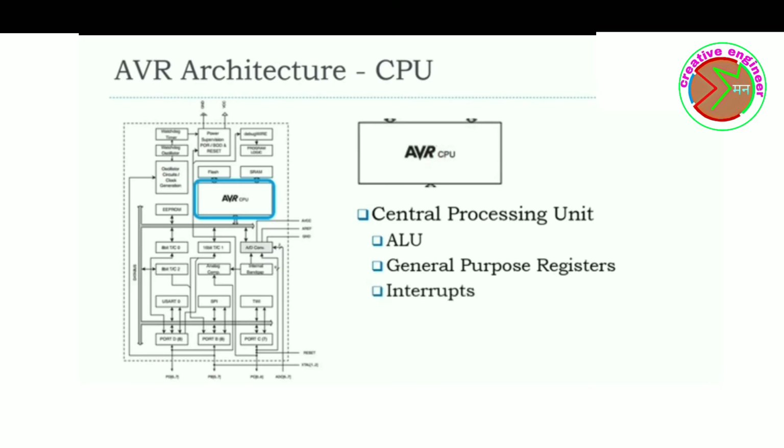Interrupts are used to alert the microcontroller for some specific conditions, by saving and suspending the normal control flow, and executing a new set of high-priority instructions. These are an efficient method to make the microcontroller respond to any external status change, compared to cyclically checking the signals from external devices, continuously. The instruction control unit fetches instructions from memory, decodes them, executes them, and stores the result. The CPU is interfaced with the memory, the counters, and the I/O ports.